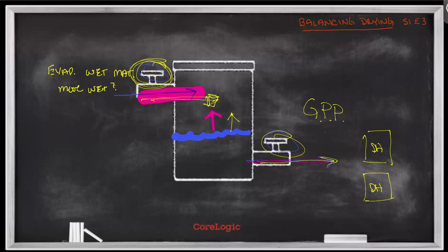Okay. So it could be this evaporation from wet material is because there are wet materials that we didn't discover. Another thing is there could be more than one source of water, right? Is there a source of moisture that was not identified? And this could be the case in more complex water damages. If the reason for this water damage event was because of frozen pipes and we found the break in a pipe, that's wonderful. But was there more than one, right? Is this because of area-wide weather events where we had wind-driven rain and we found where the water came into a building in one location, but was there more than one, right?